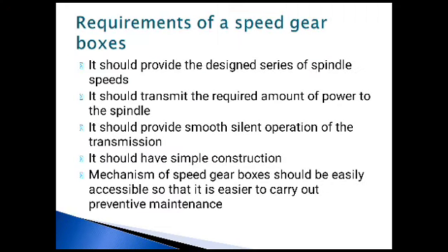The requirements of a speed gearbox: it should provide the designed series of spindle speeds. It should transmit the required amount of power to the spindle. It should provide smooth, silent operation of the transmission. It should have simple construction. The mechanism of the speed gearbox should be easily accessible so that it is easier to carry out preventive maintenance.